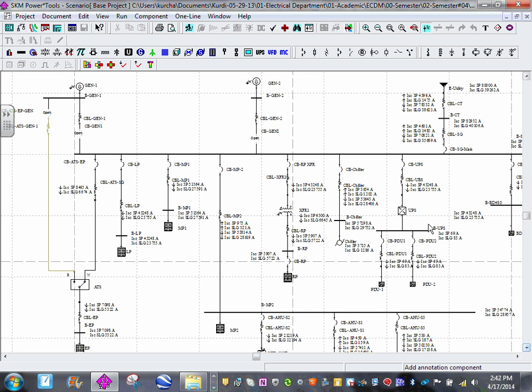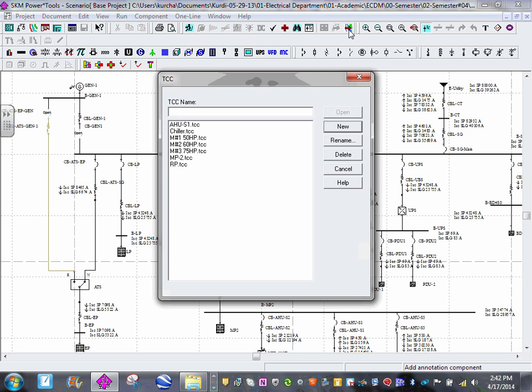What I like to use SKM for, my favorite, is when you size these branch circuits. I like to check branch circuits when I do SKM. When you do branch circuits, Mike, when you're sizing the overcurrent protection device and using an inverse time circuit breaker, your multiplier to size it is 2.5, right? 2.5 times the full load current for that motor, and that's how you size it. I didn't mean to put you on the spot.